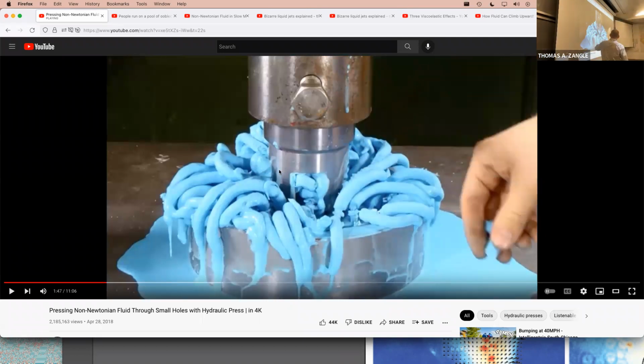So you can see what happened there, right? We said that the shear thickening behavior of oobleck arises because it's a slurry of cornstarch in water. And when you, for example, hit it kind of hard or cause a large shear stress, then you actually start expelling the water from between those cornstarch granules, and they rub up against one another, giving rise to a fluid that behaves as if it's a little bit thicker. And here, we've actually pressed the liquid water out a bit, right? So it's really changing the density of this material, and we ended up with something that's kind of like dry cornstarch worms at the end.